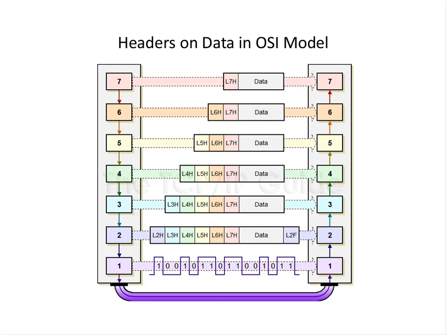So this is why we've started using 6LoWPAN and low-power narrow bandwidth networks, and we reduced the IP header on purpose so that the data as a function of the overall frame is a larger fraction so that the throughput goes up. Because in low-power narrow bandwidth networks, we don't have the luxury to have these long headers and block all the mesh and not get the data through. Because remember, time is of the essence when you're sending a demand response signal. That's the holy grail. Get the devices to quickly respond to changing situations. You can't be messing around with big headers and slow response times on a mesh.